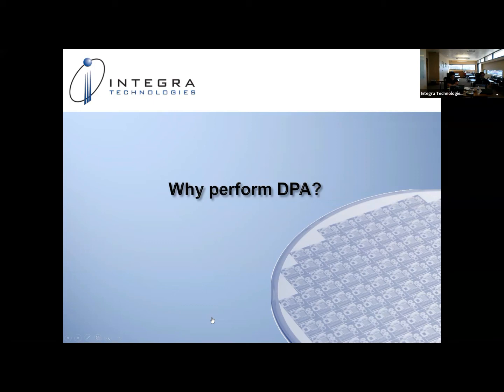The gap is narrowing, but do we see copper bond wire failures? We do, both at DPA and during quals. In the case of gold wire, because of the gold wire bonding process, we have not seen any failures over the years. Maybe the voiding issues that we see in the intermetallic between gold and aluminum, but it's very sporadic, while with copper bond wire we will occasionally see that.